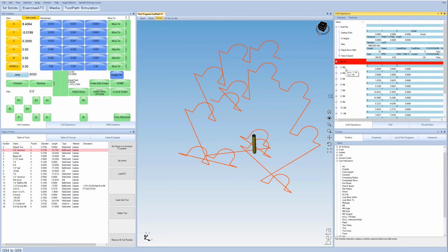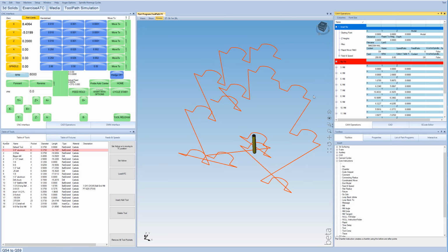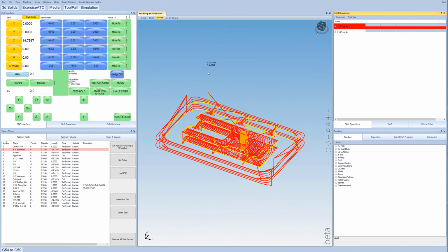Now, of course, since all these locations are pulling from the original small GCode file, I can come over here and make a change to this. We'll change the radius to 1.5. Hit update, and you can see all of these repeated patterns are all pulling from that original GCode file. Okay, and so that worked out well.